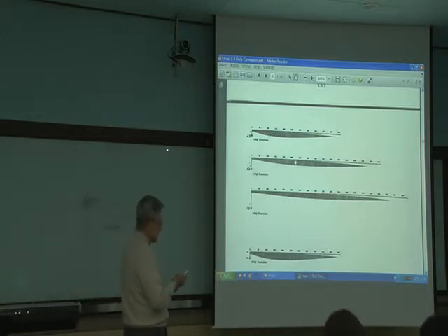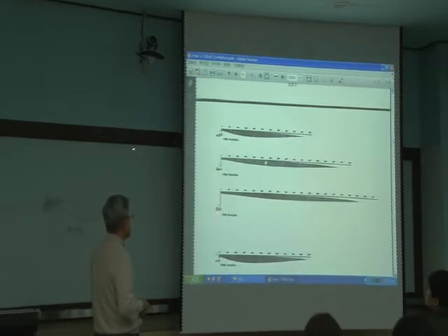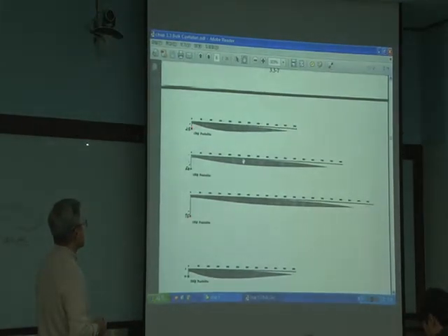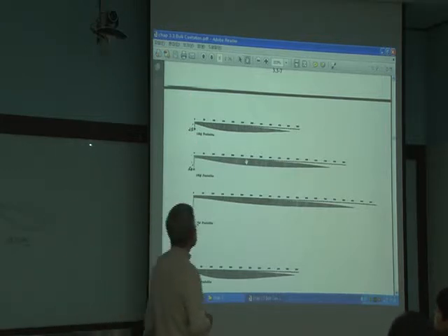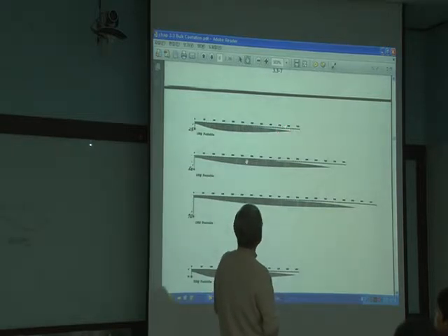So this is pentolite, a type of explosive. This is 100 grams, and the charge depth is 25 feet below the free surface. This is 50 feet. This is 75 feet. And look at the spread of the bulk cavitation. This is the center line. You can think about the axisymmetric rotation about this vertical axis. So here is for 25 feet charge depth. This is about 500 feet long.